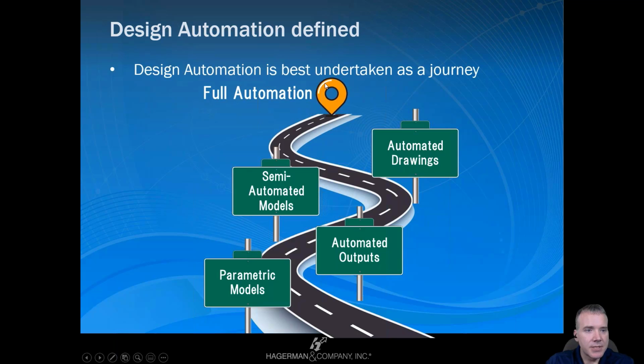This is the last step because you can do automated drawings even with iLogic, but you can't get to the point where you're fully automating the process without programming knowledge. Because someone has to code an interface, someone has to, if you're using Inventor, direct Inventor to open this assembly and modify these parameters and save off this PDF.